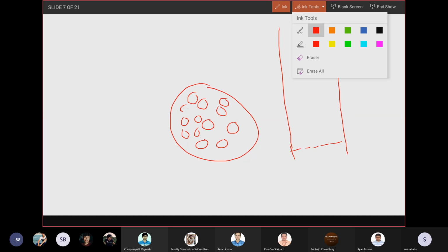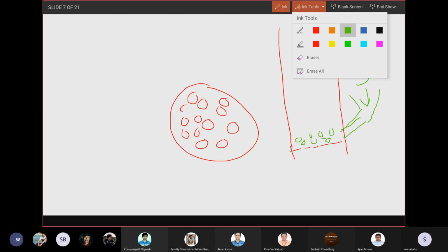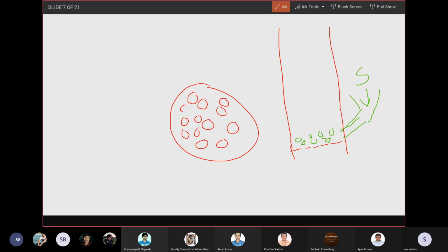Now, to this distributor, in this vertical pipeline, there will be a hopper or a funnel through which the particles, the solids, will be fed. When you feed the solids, they come here and nicely settle down on the distributor plate. If you don't have a distributor plate, what will happen? They will continuously fall downwards. So to make a stable platform for the particles to not flow down, there is a distributor plate.